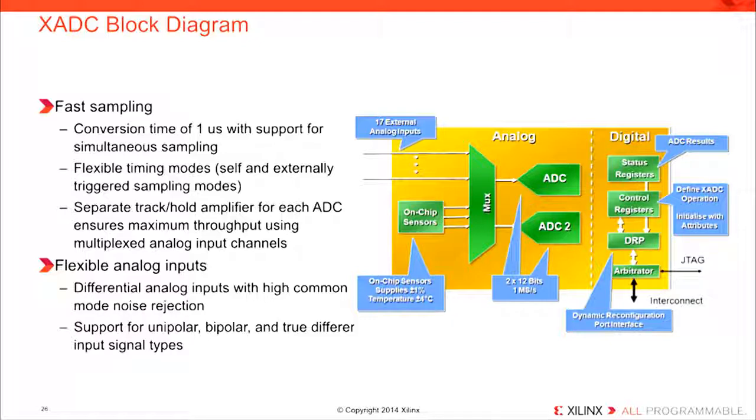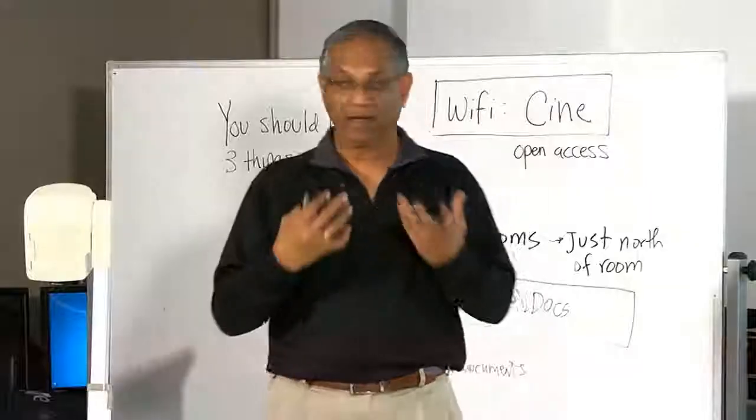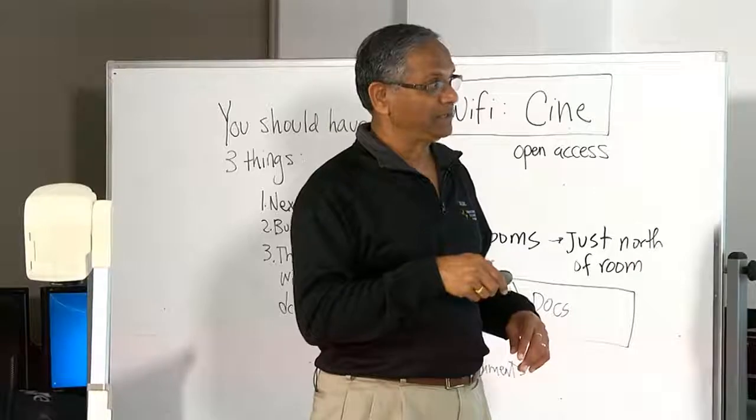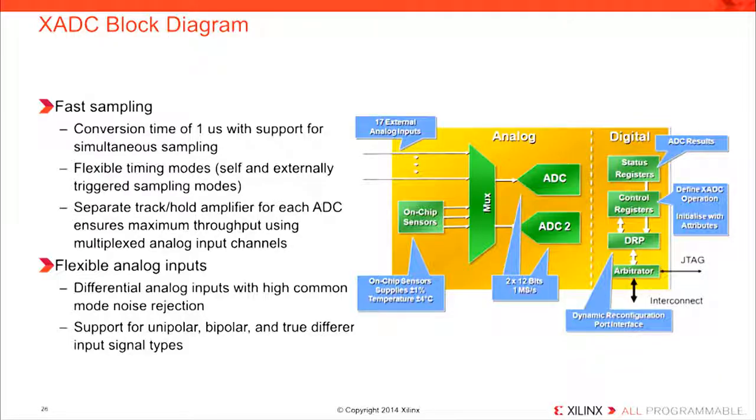So, you can sense the temperature, you can sense the voltages through these on-chip sensors and create an interrupt or alert, so that the system can take corrective action. And conversion takes place through the A to D converter, and then the conversion output can be accessed through the data register. Conversion control configurations and status registers will allow you to monitor whether conversion is complete or is in process.